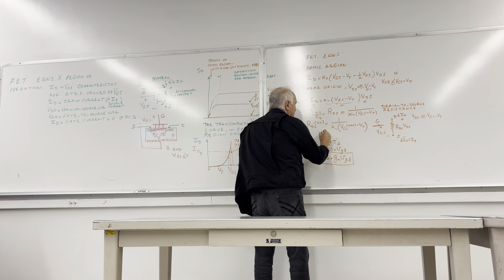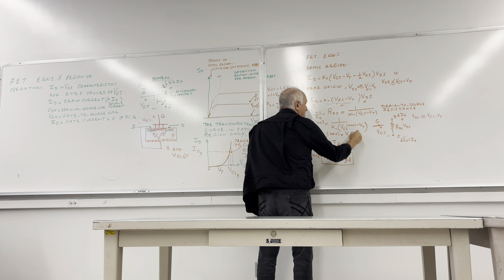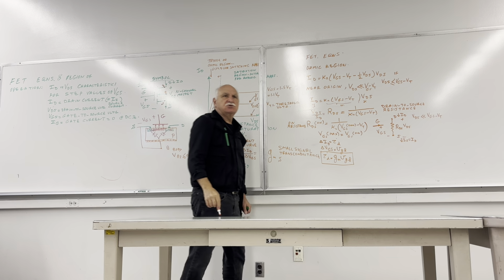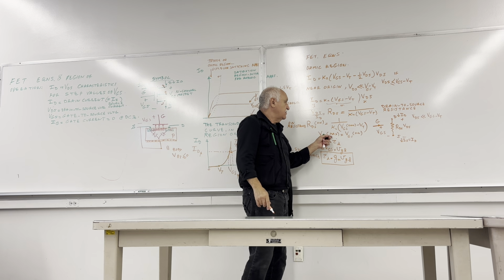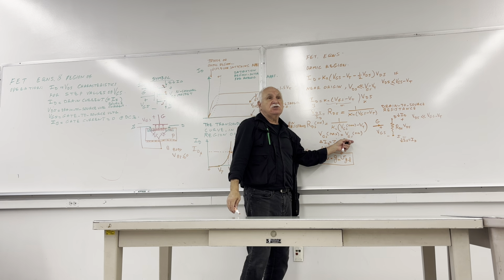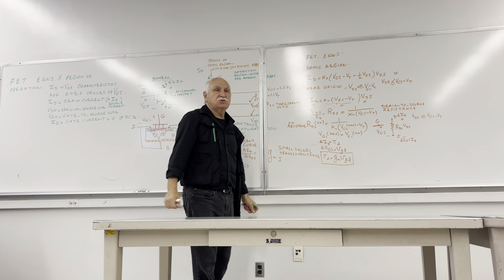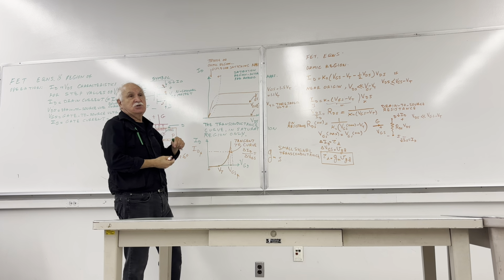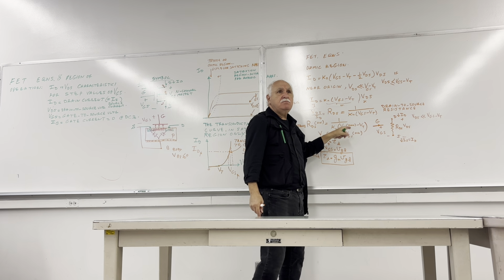This VGS max, because it's a maximum, is VGS on, the recommended on voltage. So go by that, the recommended on voltage. Maybe they can take 16 volt for the maximum before they are busted, the breakdown. If the manufacturer says 16 volt is breakdown, but VGS on is 12 volt, go 12 volt, no more than 12, because it can break down the transistor. There are chances of it. You will get smaller resistance, definitely, if you go higher than VGS on, but it's risky.